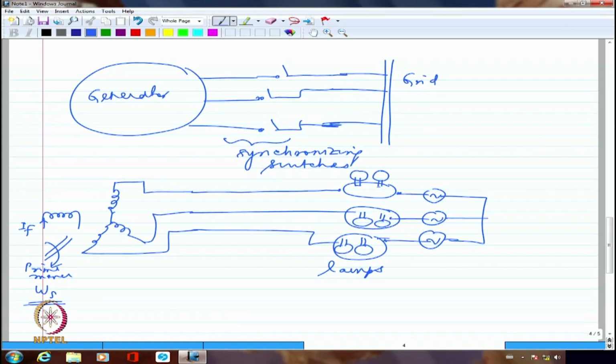Right? But it's very difficult, rather impossible for me to get the exact matching like that. Because I may think that it is 50 Hertz, actually grid frequency may be 49.98 Hertz. Still there is a small difference. Can't help it. And what you measure as the speed may be 1500 RPM. Actually, the indicator shows it is 1500. It can be 1498 for what you know. Measuring error there can be.